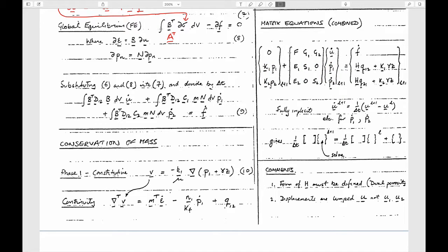It does. When we talked about single porosity poroelasticity, we had these terms here. We had deformations and fluid pressures. They only operated on these terms. And this was the stiffness matrix. This is the storage term, just due to expansion of the fluids in the pore space. And these cross-coupling terms were these symmetric terms. They were the transpose of each other. One says how much body force is applied if you put a fluid pressure in there. The other one says how much fluid is squeezed out if you deform it by some amount.